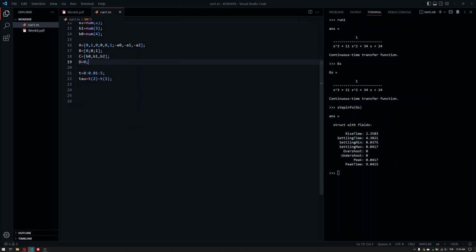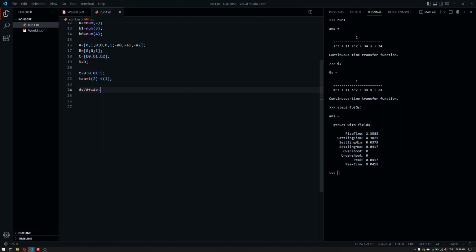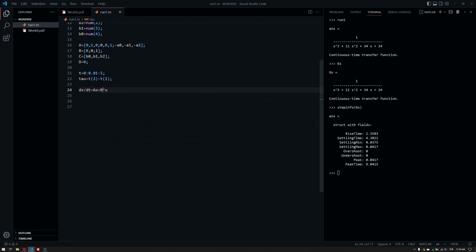Now, we have defined a time vector. Just for the sake of simplicity, I also calculated the sampling time here. So what I need to do, and what the zero order hold method is in a nutshell, is that we have an equation that looks like this, x dot equals a times x, and then we have y equals c times x plus d u here, where we don't even have d because it's 0, but it's generalizable here.